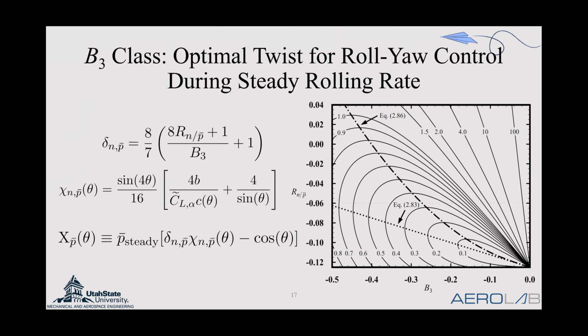So another stupid question. So adverse yaw and proverse yaw. So actually, you're turning in the same direction, but do you need different controls? So maybe the pilot will feel different, but otherwise, is there some other benefit? Yeah, so if you want to turn to the right, you usually bank the aircraft because your lift is the largest aerodynamic force, right?